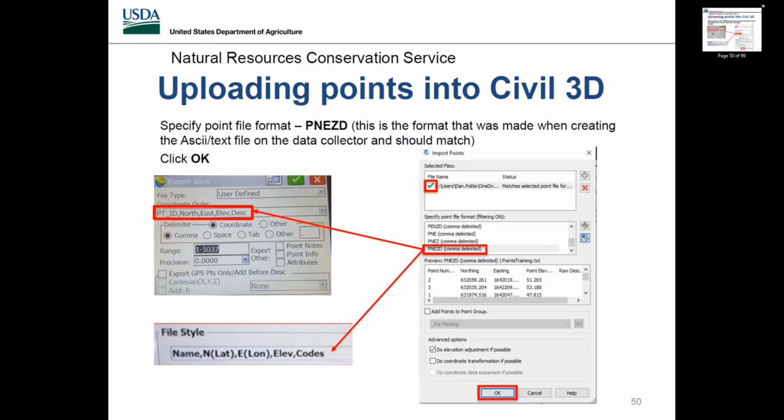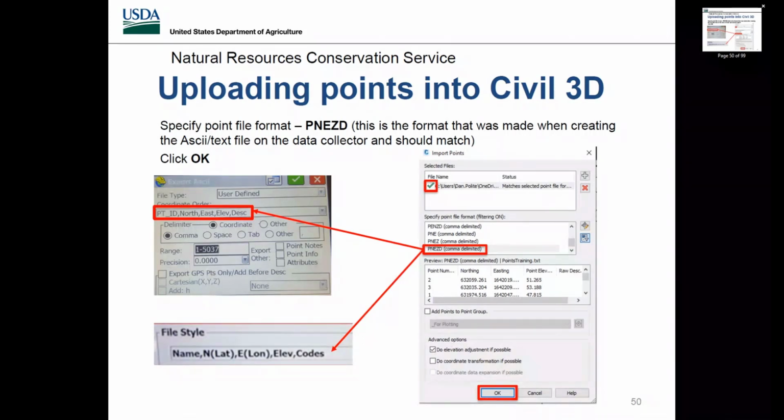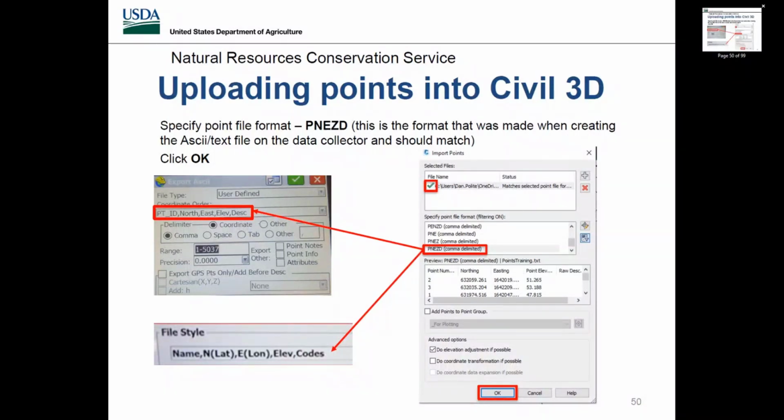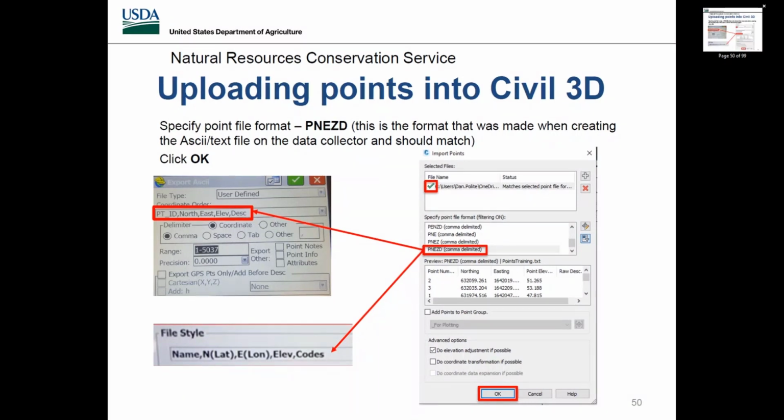That's another great point, because when you're doing GPS, you have to have a minimum number of satellites to start taking shots. And the longer you let that base station sit there and gather information, get the correct curvature of the earth and everything else, the more accurate it is. If you just set it up and start taking points, it could be that far off. I was always told a minimum of 15 minutes, but it's recommended to do 30 minutes to set that base station up and let it gather information before you even start surveying. Now, if you're using RTK, it's a totally different ball game. You're already connected to a base station that has the corrected elevations.